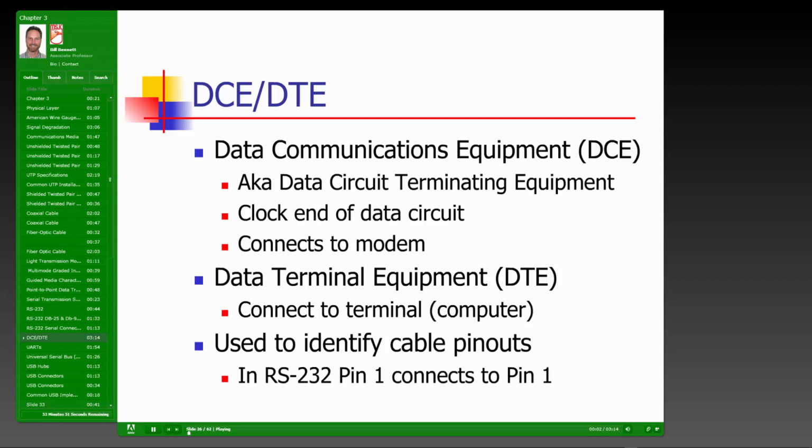So if you go back to that previous slide and you look at the graphic, you'll notice that on the 25-pin connector, one pin represents the DCE channel and another pin represents the DTE channel. And in the communication process between two devices, one device is responsible for the timing of the message. This is synchronous communications that's going on here in this RS-232 circuit. And so what that means is that one device has to define what frequency we're operating at.